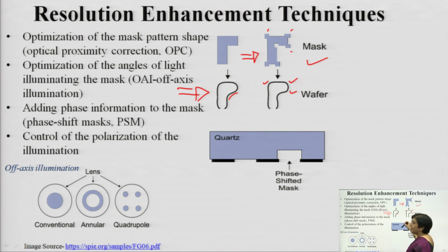Similarly, away from the light source, the mask dimensions will be changed for excess illumination, especially in X-ray lithography, to eliminate the proximity effects or the impact due to the angular beam getting projected onto the wafer substrate.